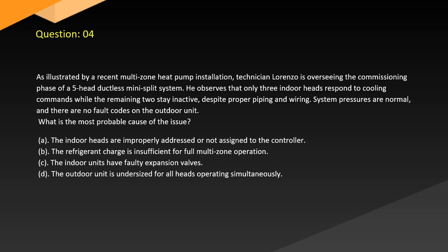A. The indoor heads are improperly addressed or not assigned to the controller. B. The refrigerant charge is insufficient for full multi-zone operation. C. The indoor units have faulty expansion valves. D. The outdoor unit is undersized for all heads operating simultaneously.